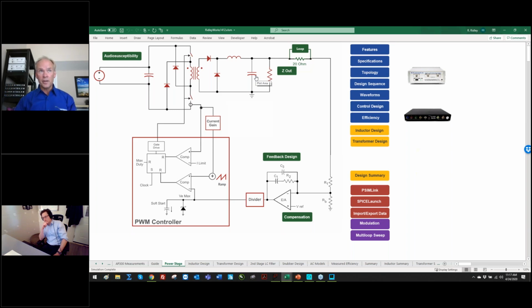And then at the end of it all, you say, well, okay, I'm going to use these switches with the right on resistance. I'm going to use the controller that will work at that frequency range and give me the features that I want. But the size of the converter is transformer, inductor, capacitors. And everything else kind of shrinks and disappears. So, we're not power limited there. However high you want to go in current in these inductors and transformers, it will go there for you.